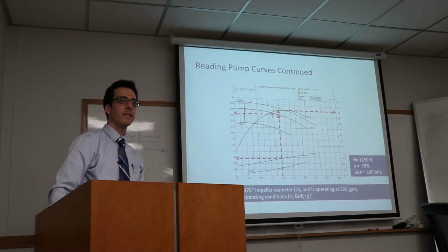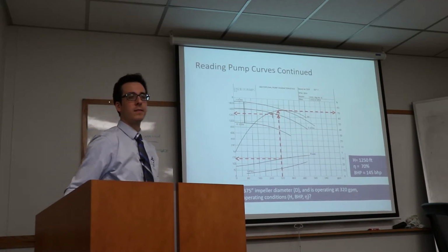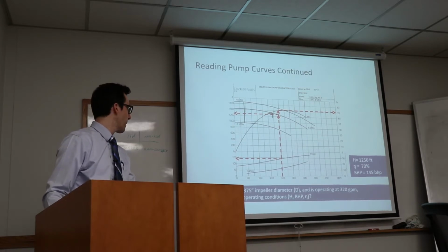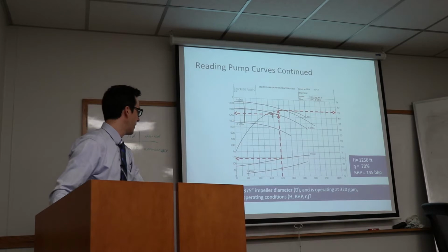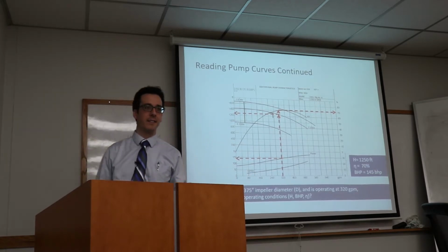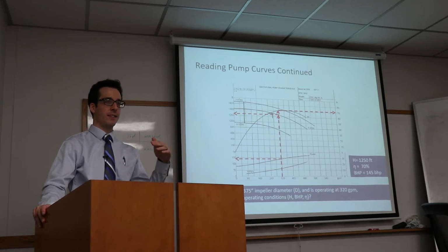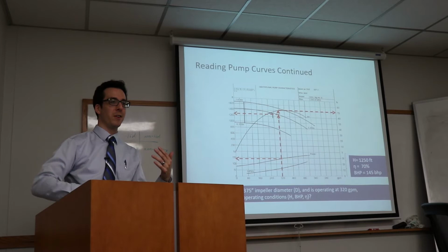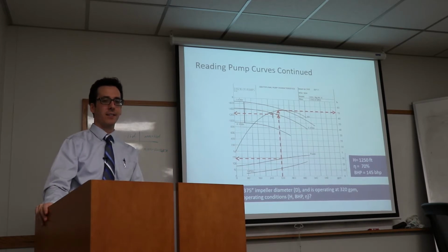Yeah, in the back. Have you ever run into issues in practice with the bottom curve that we need to worry about in this class? The net positive suction head, we won't worry about it here. So in one of my early slides, I showed that you have to have a certain amount of water above the pump in order for it to function. That's what the net positive suction head is.